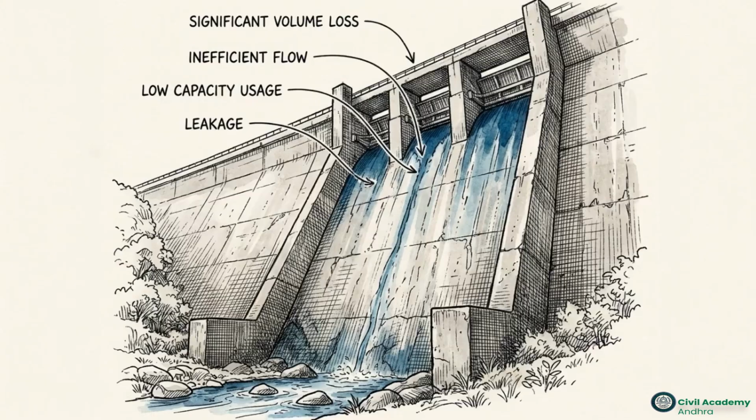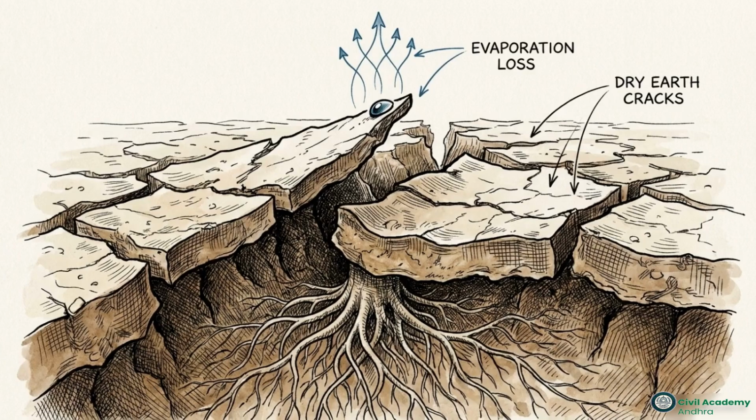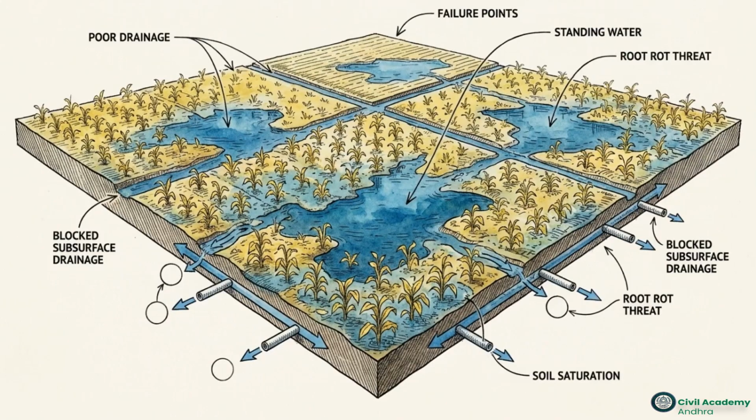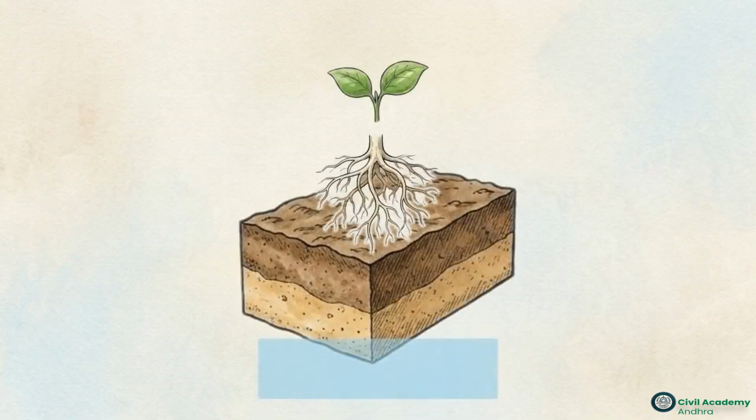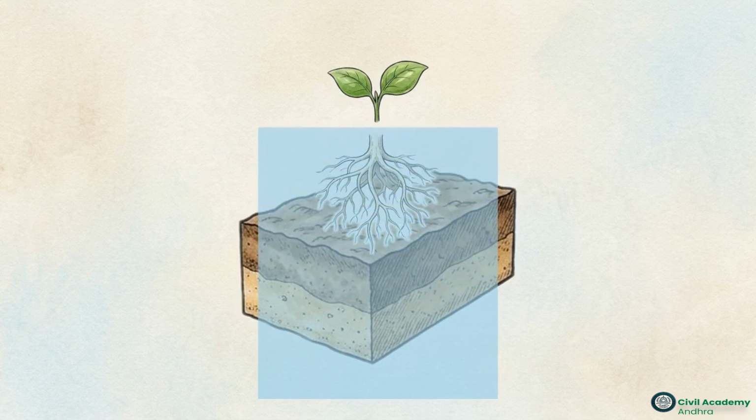If you fail to scale up your dam release calculations using these exact efficiency factors, the water you send will vanish into the soil long before it reaches the roots. On the flip side, oversupplying that gross irrigation requirement without establishing adequate drainage is equally destructive. The water table rises, choking oxygen from the plant roots and depositing heavy white salt crusts across the surface. Physically, this waterlogging is an inversion of the soil sponge. The local saturation capacity overflows upward, with the groundwater rising directly into the root zone.